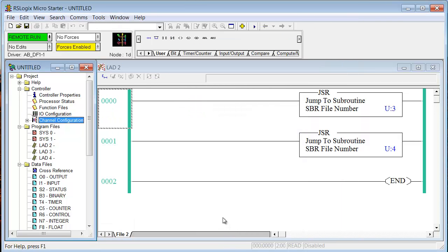Now you have your Ethernet port on this controller with a known IP address. At this point, if you want to communicate with it, the Ethernet address on your laptop, remember, has to be 100, 100, 100, and something other than 100, with a subnet mask of 255, 255, 255, 0. Close this.